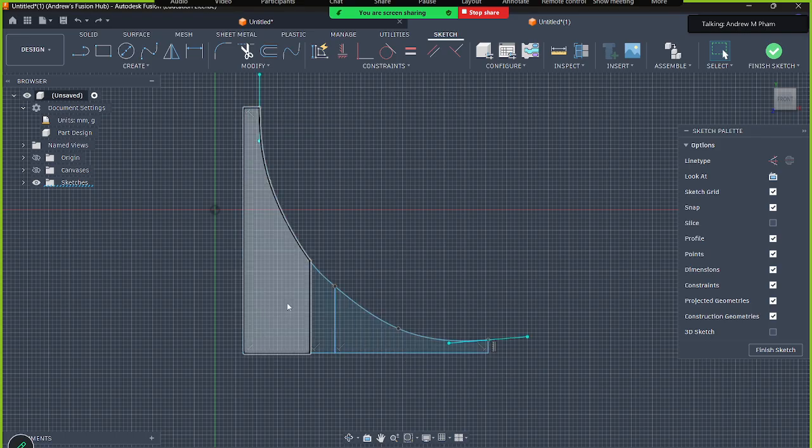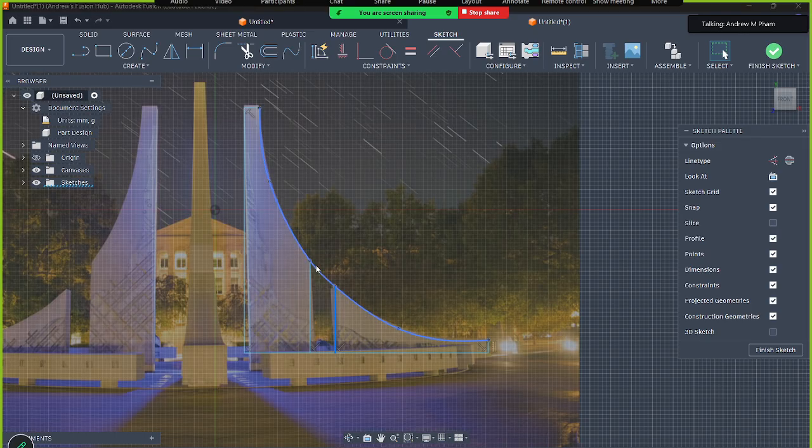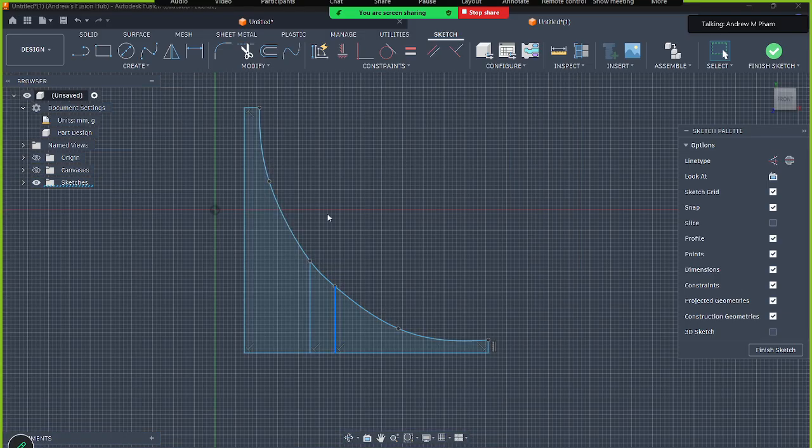So for the trim tool, you want to make sure you have these vertical lines first. So I created those points there and there. That kind of overlaps with this point, at the end of this one, the start of there. Once you have those in, starting at this point, ending at the bottom line, you trim it with the trim tool.